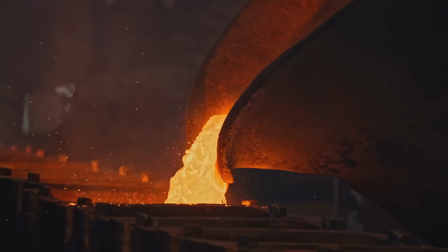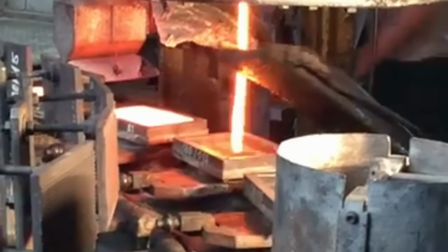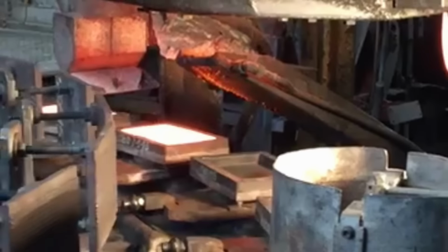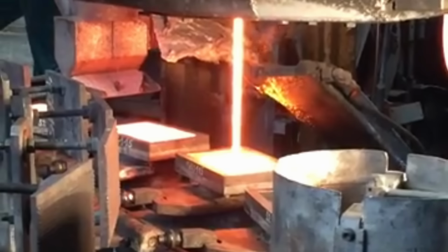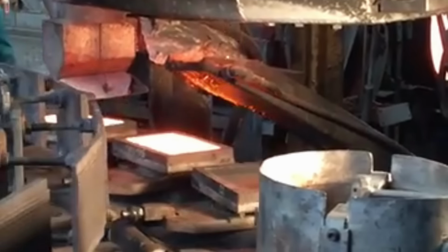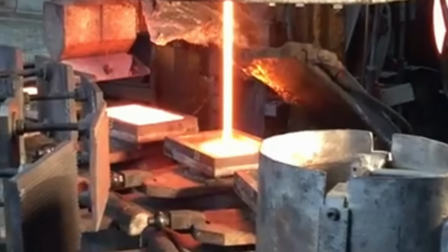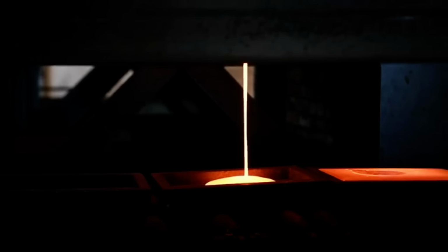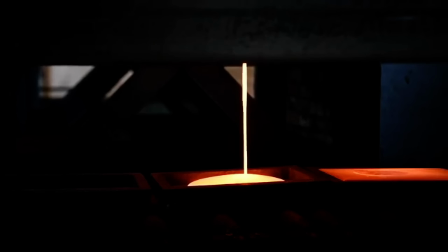But the molds aren't cold. Much cooler is relative, as to avoid shock cracking the molds, which are typically made of steel, we preheat the molds up to about 800 degrees Celsius, near the working temperature of steel. The goal is to get these two things as close in temperature as possible, so we heat the molds as much as we can without damaging them, and then cool the melt as much as possible while still keeping it pourable. And by doing so, we are able to avoid forming crack shocks in both the cast product and the mold as well.